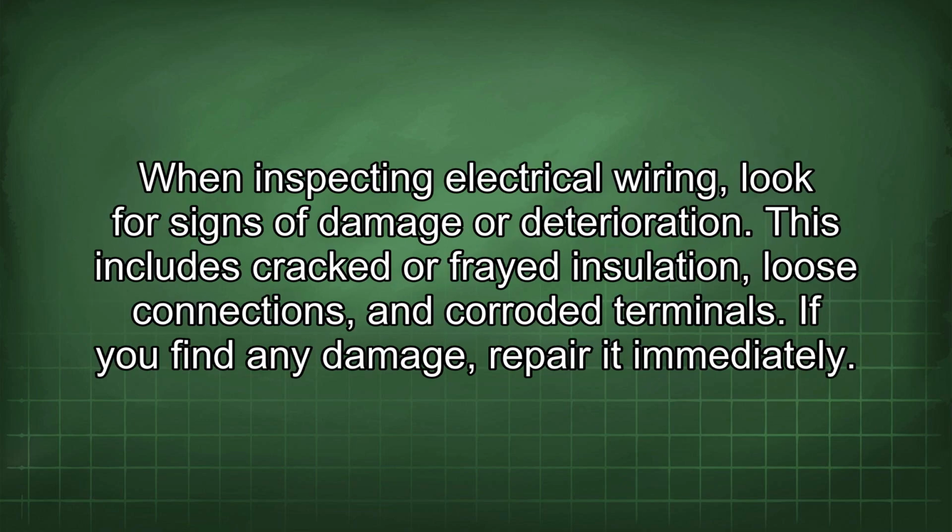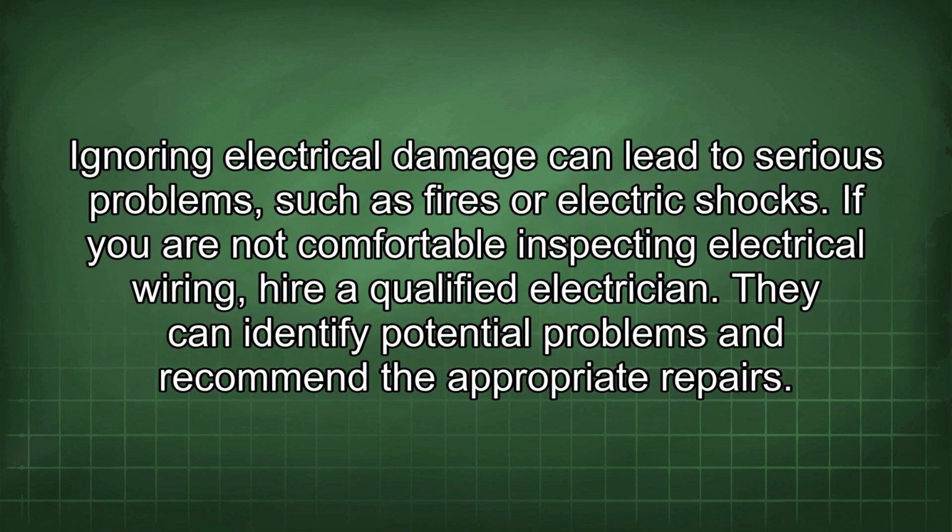When inspecting electrical wiring, look for signs of damage or deterioration. This includes cracked or frayed insulation, loose connections, and corroded terminals. If you find any damage, repair it immediately. Ignoring electrical damage can lead to serious problems, such as fires or electric shocks. If you are not comfortable inspecting electrical wiring, hire a qualified electrician. They can identify potential problems and recommend the appropriate repairs.